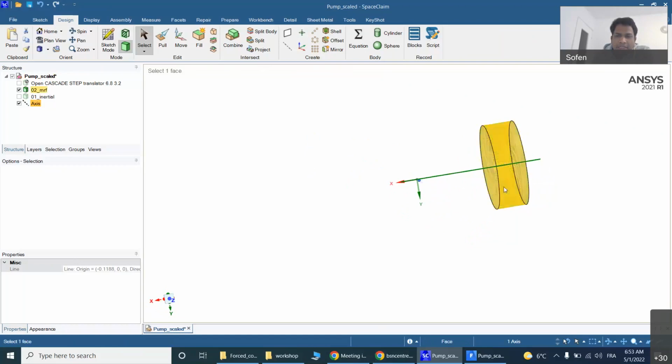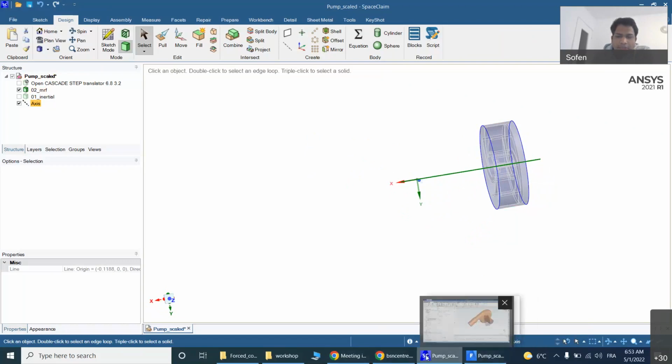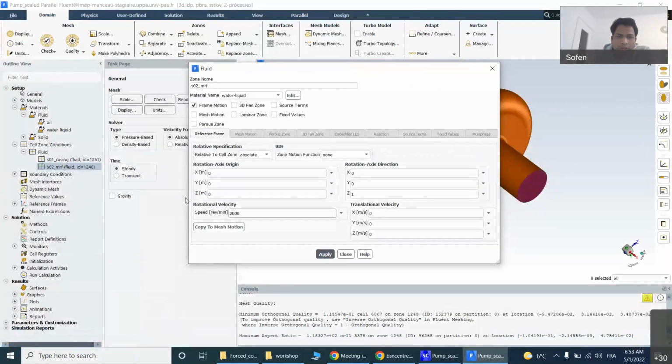If it is a random axis, it will show you the direction cosine for that one, and you can put it in. But it's the X axis, meaning X1. Just put it in and come to Fluent. Rotation axis direction: it is rotating around the X axis, X1, Y0, Z0. Otherwise, if it is an inclined surface, you will get the axis information as direction cosines like 0.5, 0.5. But it is rotating around the X axis, that's why I put X1, Y0, Z0, right?